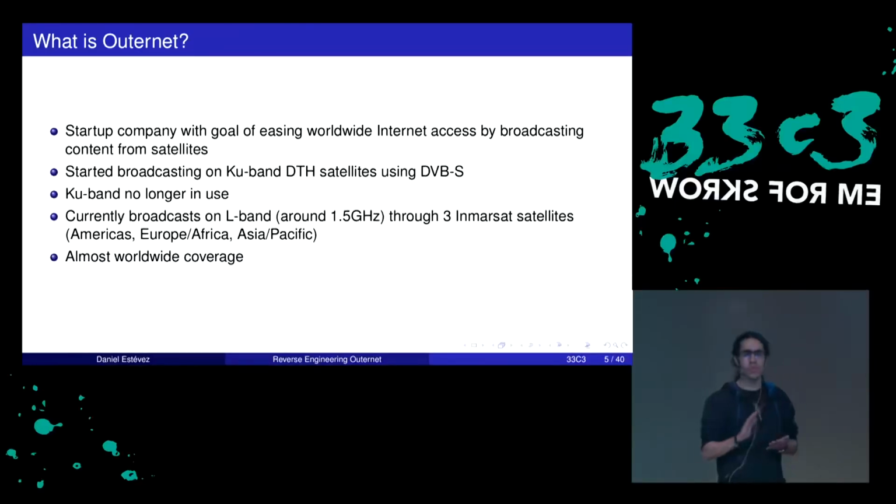And they started broadcasting using digital television satellites. So you could use the same equipment that you would use in Europe, for instance, to receive digital TV from geostationary satellites. Indeed, you had a set-top box. And this works because in DVB-S or DVB-S2, usually you embed digital video, MPEG or whatever, but you can embed all sorts of content. So they embedded files into that.